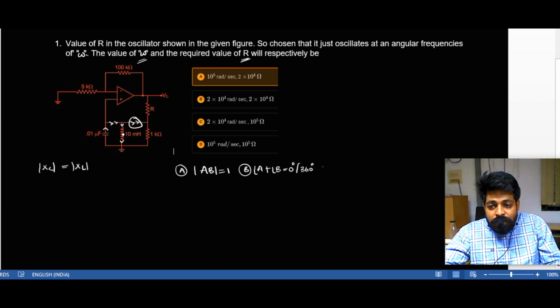So the entire energy will be transferred to this, and after that the inductor takes the entire energy from the capacitor in the form of electric field to magnetic field. That entire energy will be transferred again back to the capacitor. That is how the energy is shared between the two components. In that way, once the energy is transferred and received, positive and negative half cycles are repeatedly generated as an electrical signal across the capacitor. So this is nothing but oscillation. But to maintain a sustained oscillation, an amplifier is connected to the tank circuit.